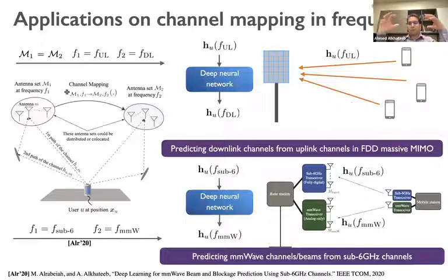What I believe is that you would probably have a hybrid solution where you can use machine learning to reduce the dimensionality of the problem. So for example, the base station can use machine learning models to say, okay, I have a 64-antenna massive MIMO base station, but probably this 3-4 dimensional subspace is where 90% of the energy of the channel is. And then it can design its precoding and training pilots to only focus on these 3-4 dimensions. This may reduce a lot the training overhead as well as the feedback overhead.